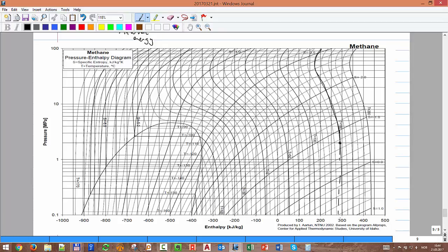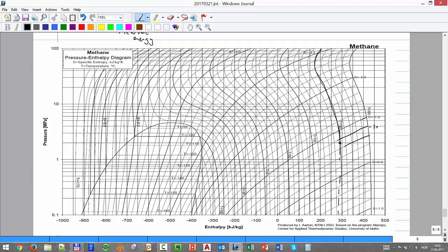So you knock it down, and at this particular point you will have that enthalpy, and those are the entropy lines. Don't worry about them too much. For that case, for example, you will have an entropy a bit less than minus 8.8. It's like I pre-computed, I took methane, either I measured all the properties in the lab, or I took an equation of state and pre-computed and put all of them in a graphical way. You see it's kind of messy with all of these lines, but we will see right away that it's very powerful.